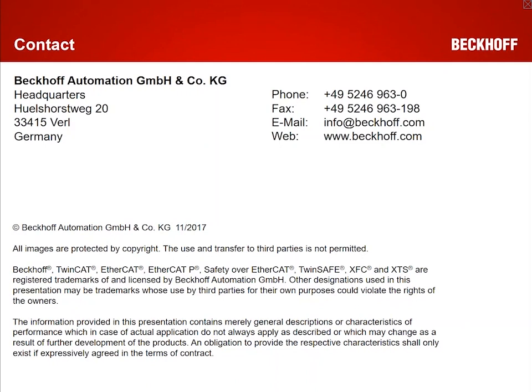One question is, is it possible to call existing PLC code from the Simulink model? Today I need to say no. Only the other way around. So we can only call the TCCOM objects from the PLC. The other way around would be great to have, but it may need some very huge work behind the scenes.